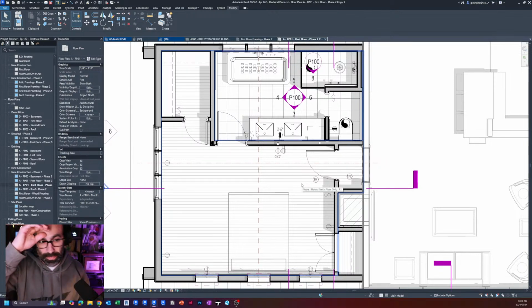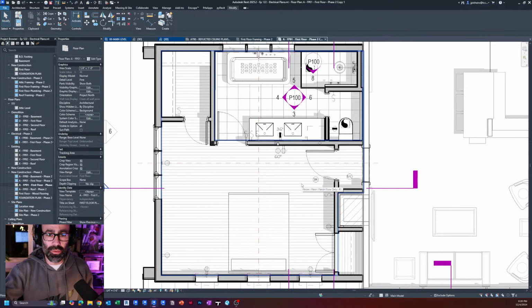And so that alone, like I said, if you do that right away, you're already making your electrical power planning much easier just by using these families. Maybe there are other families out there, and that's fine if you find them, but using the right families will help. Unfortunately, that is not the out-of-the-box outlet and switch families, right? They don't have this ability with annotated objects within them the way Brenton built them, so that they are seen wherever you need them to be.